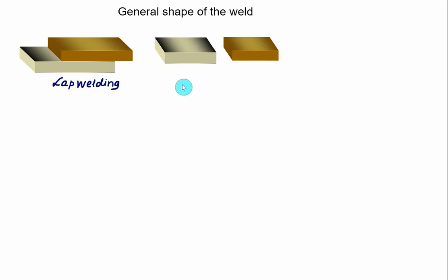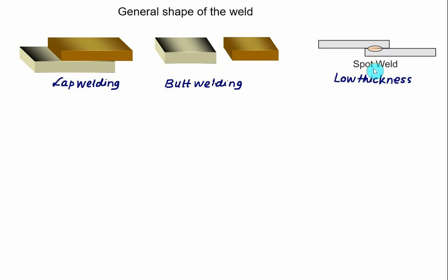welding. If the thickness of the plate is large, you have to use arc welding, and if the thickness of the plate is small, then you can use spot welding. In spot welding, we have 2 plates, electric current is passed, and because of the resistance between the interface of the 2 plates, a localized heat is developed. Once this heat is developed and fusion starts, we form a nugget. Once this nugget is formed, force is applied externally to get a spot weld.